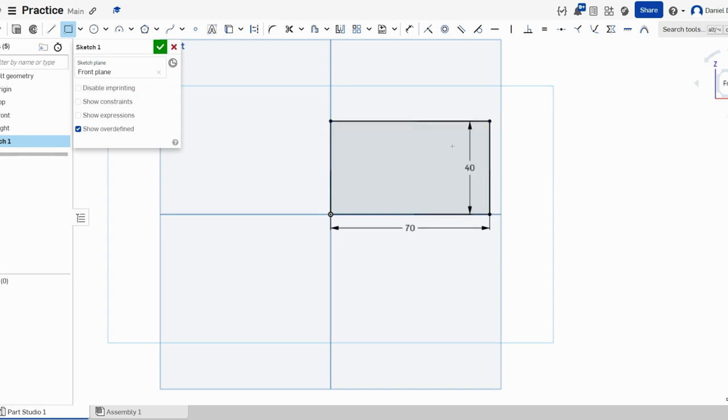Now you'll notice that my lines here have gone from blue to black. That's because they have been constrained. I have given them exact dimensions, and now that's not going to change unless I go in and specifically change it. That's a very valuable part of CAD: dimensioning things and having your pieces constrained to other parts so that they stay together. And when we make adjustments, things move together. And again, we'll get more into that later.